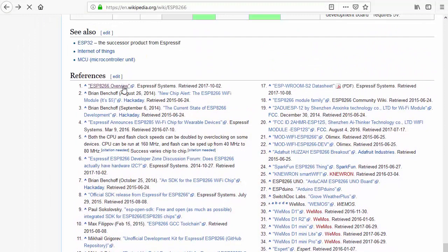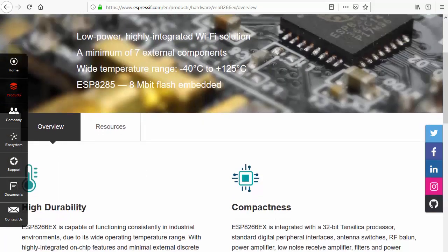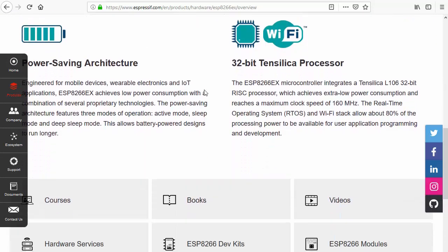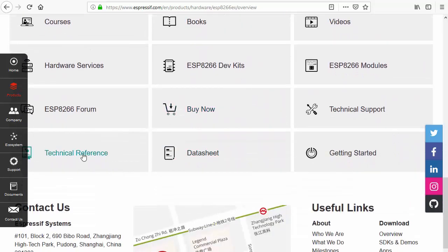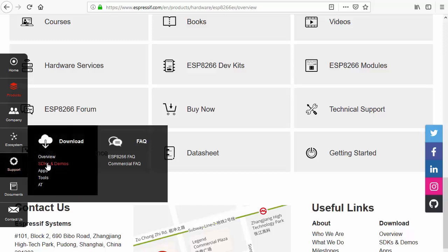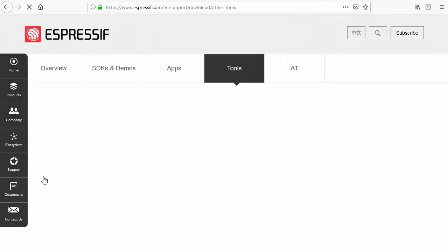The ESP8266 microcontroller is designed by Espressif. It's a very capable and fun little microcontroller, however, not sufficiently reliable for industrial applications in my opinion. It's based on the Tensilica Xtensa processor. Competing Wi-Fi enabled microcontrollers that are based on ARM Cortex-M architecture have recently become available in the market, but I haven't had a chance yet to try them out.